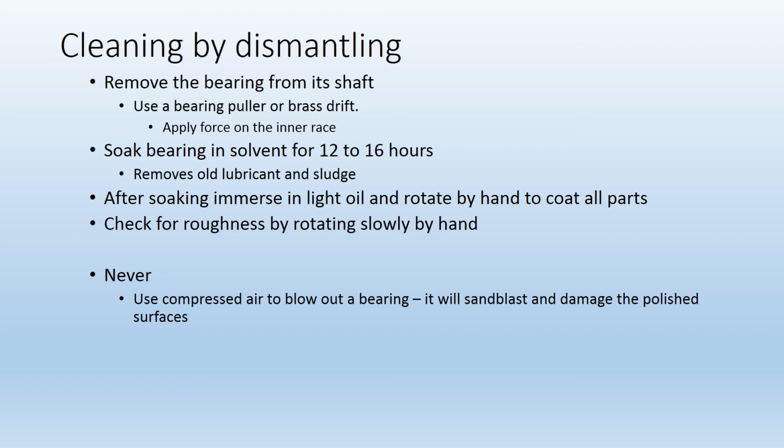Never use compressed air to blow out a bearing. If you do use compressed air, it'll have a sandblasting effect on those highly polished, hardened surfaces, and it will reduce the life of the bearing.